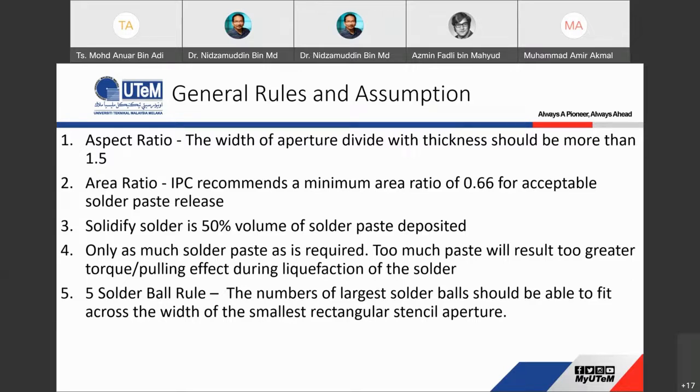So the fourth one is a very optimum amount of solder paste that we print on the PCB pad. Most of the time, for chip components, we have an issue with tombstone, non-wetting. The force between the left and right termination, we want to make sure is very minimum.